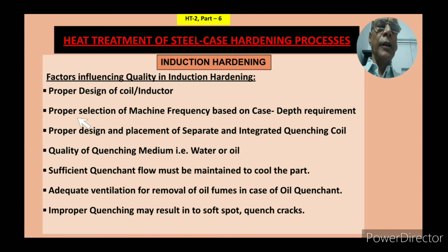Second point is proper selection of machine frequency based on the case depth requirement. This I have already explained in my previous slide, that based on the case depth requirement, you have to select a proper frequency power source, as per the requirement of the case depth.